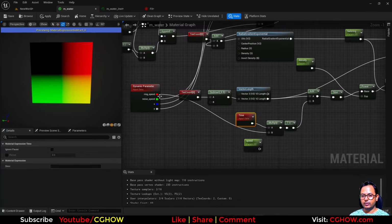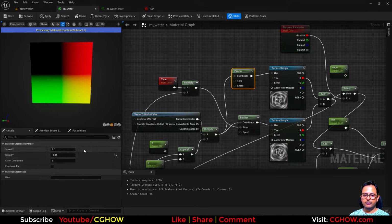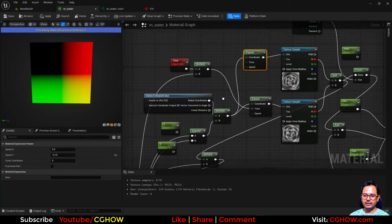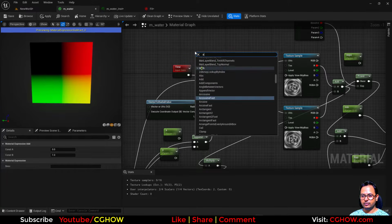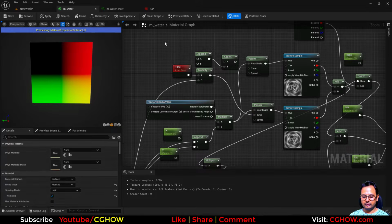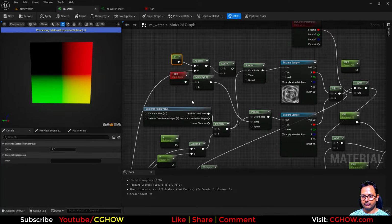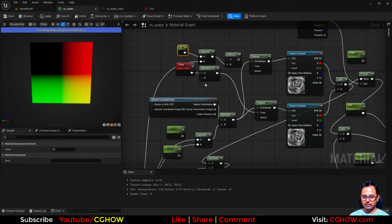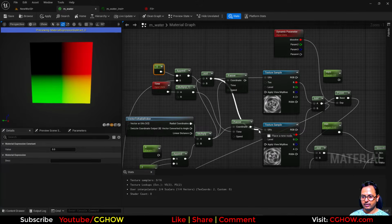So what you can do, you can use that value here. And here, because we are animating the y value and negative, what you can do, you can take a add value and then append value. And in the x, I'll put the 0. And in y, I will use that value, my dynamic parameter, this noise speed. And this will come here, and this will go there.